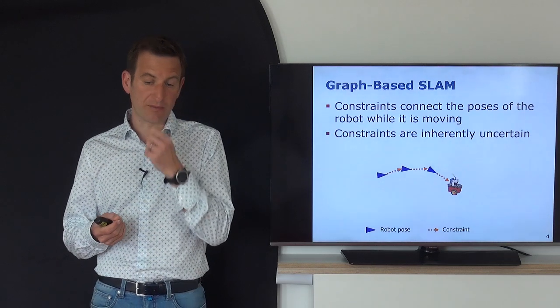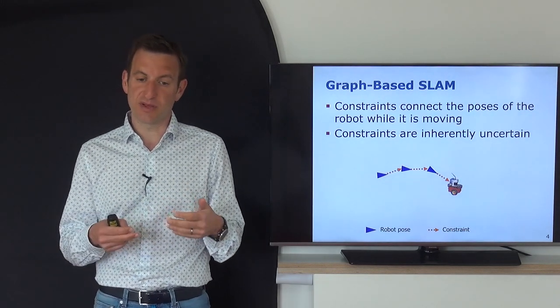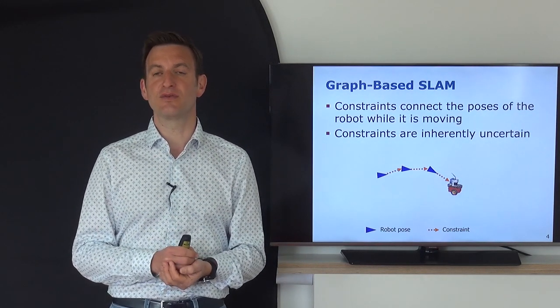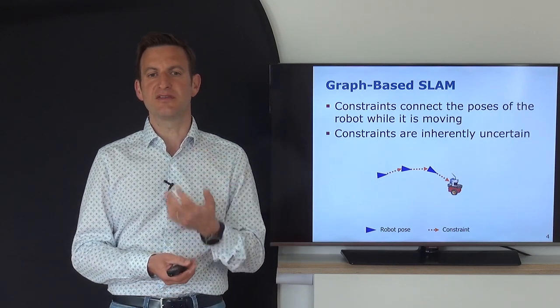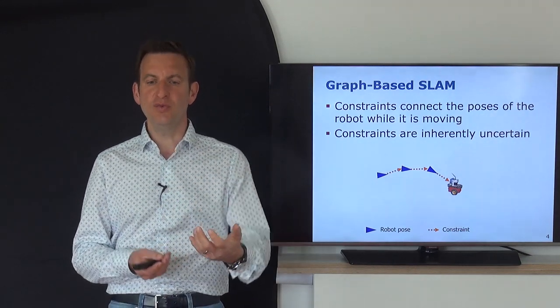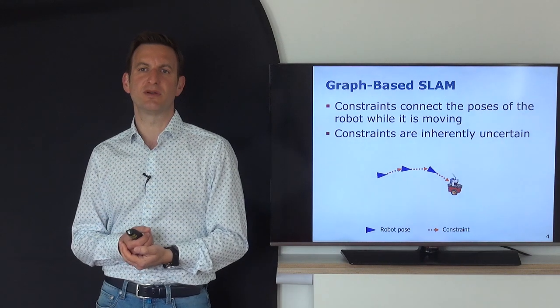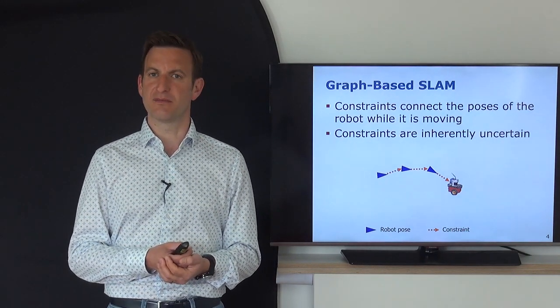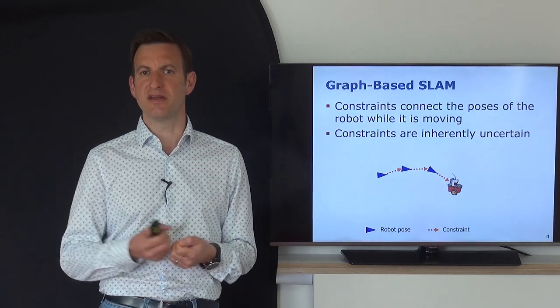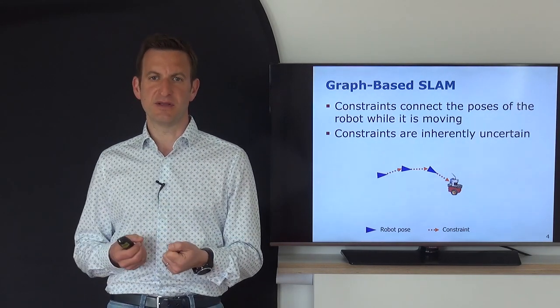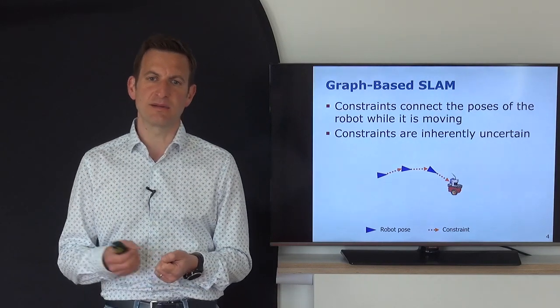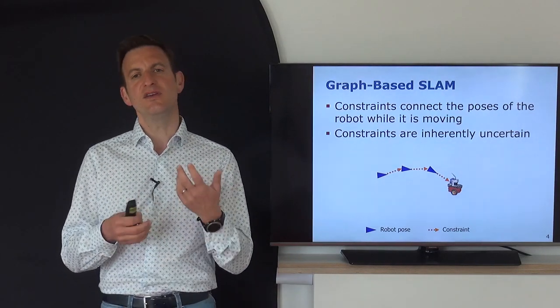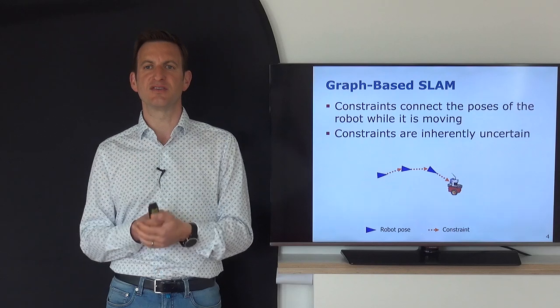And so, because the revolution of the wheels is related to the distance between those two nodes, this allows you to say, okay, pose 2 is, for example, a meter away from pose 1. You're typically uncertain about this information, because maybe it's 1 meter and 2 centimeters, or 95 centimeters, or 1.20 meters, or a little bit more to the right or to the left. So you see there are some uncertainties because this information is not perfect.